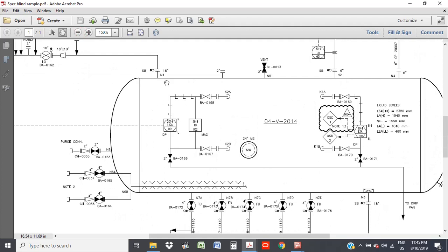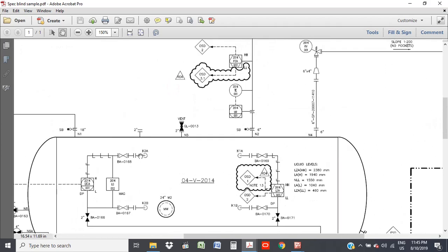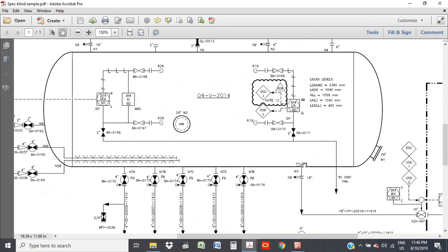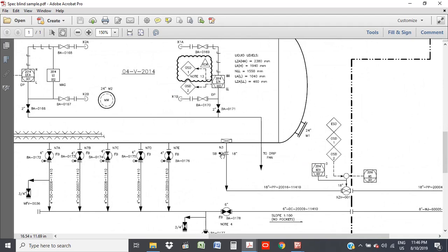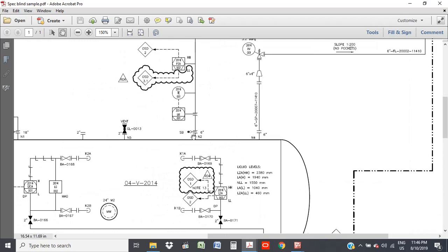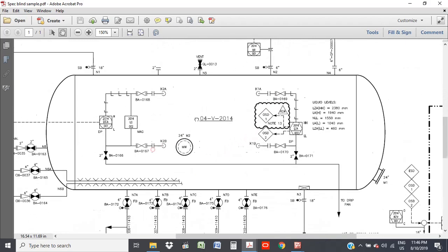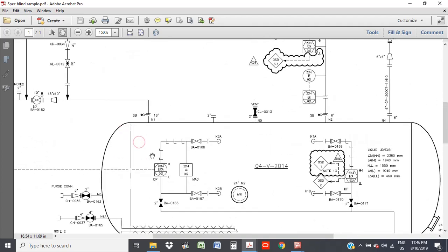So if you want this vessel out of service, you would just open the flange, swing the spectacle blind across, and bolt the flange back in place, and ta-da! Have no flow into this vessel. You can see it at the end of this nozzle here also, and you can see it here at the gas outlets. It's used very much. You come across it a lot.